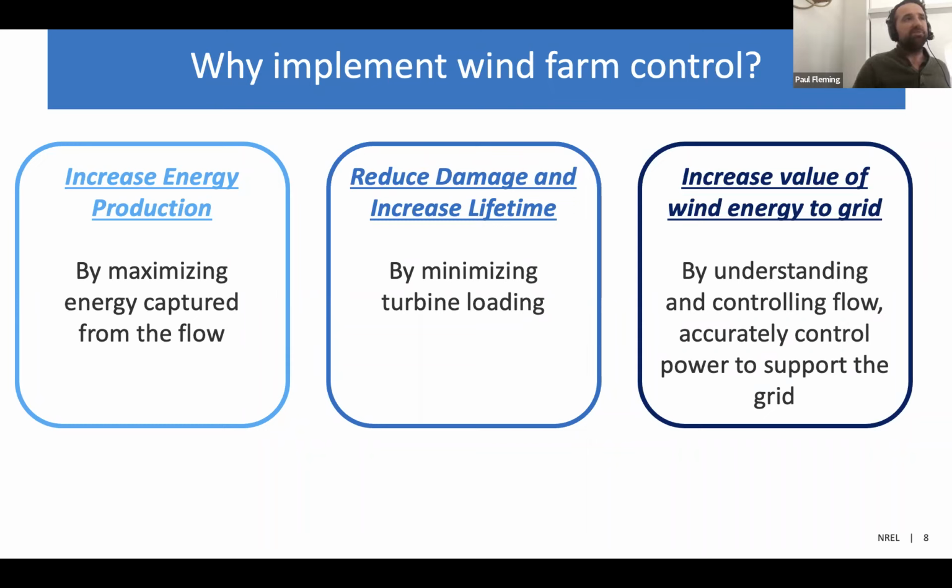The increased energy production that can come from better achievement of yaw alignments, something we'll talk about later, or it could mean mitigation of wake losses. A recent paper, for instance, cited that offshore US farms might expect to lose 1/3 of their energy production on an annual basis to wakes. So there's a lot of upside to trying to reduce the amount of energy lost to wakes.